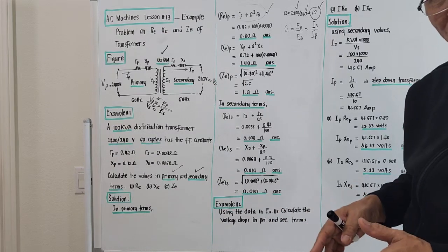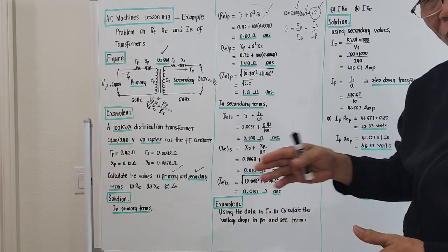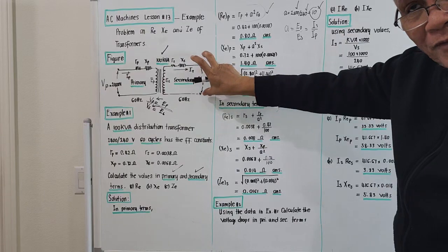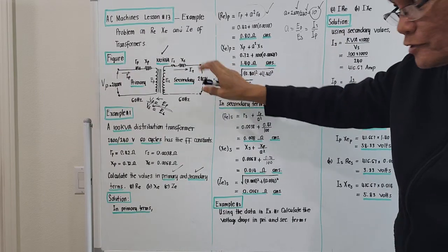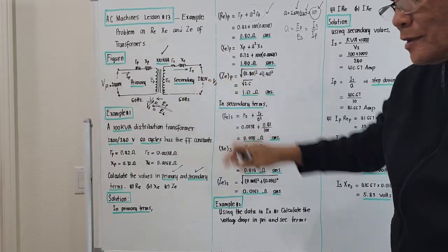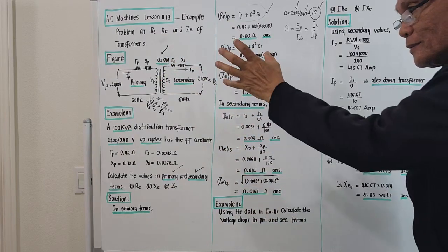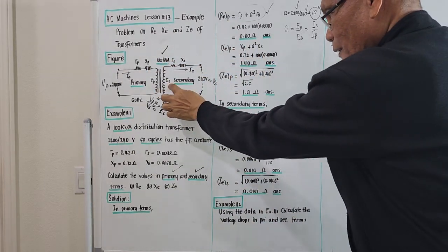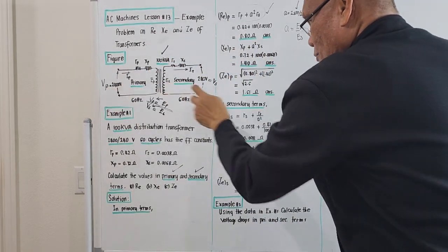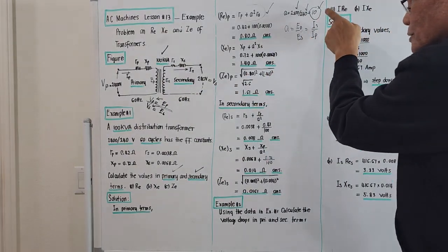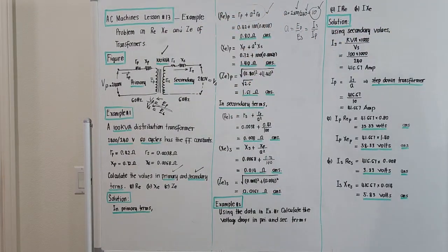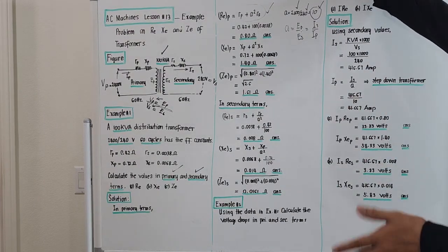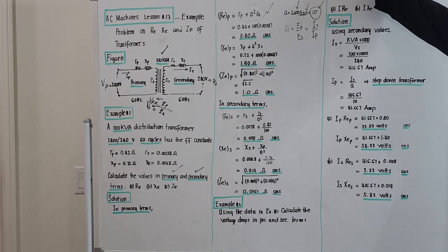If your load may be an air conditioning unit, which is 240, your service entrance voltage should be 240 instead of 120. Okay, I will repeat it. The given distribution transformer is step down, 2400 to 240. Okay, the ratio of transformation is there. Let's proceed with the computation. That's a little bit of storytelling, but we are discussing concept.